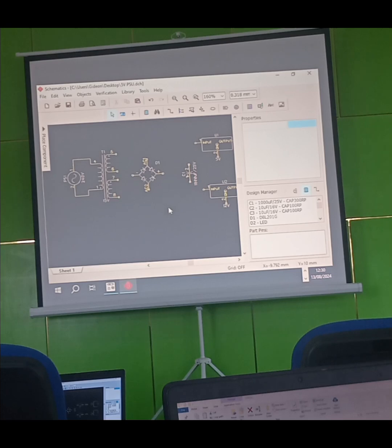Okay. So now let's say we can use 2 diodes, but what should our transformer be for each side? What do you suggest? Okay, we have 2 secondaries. So should one be 12? 2 for what? 2 diodes. No, let's discuss the transformer first. One should go for the 5 volt, one should go for the 12 volt.